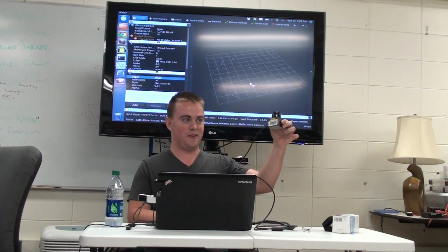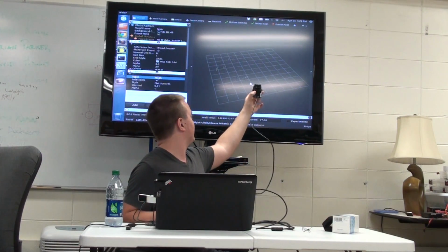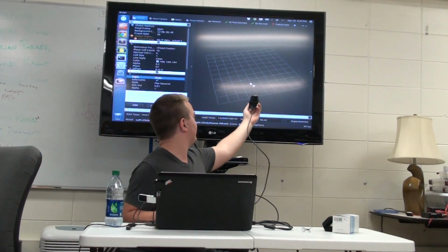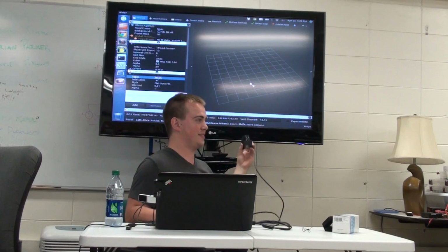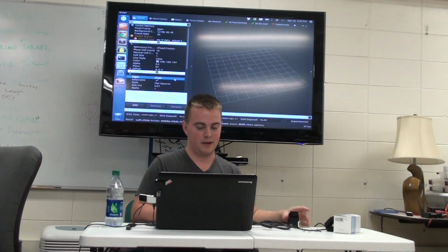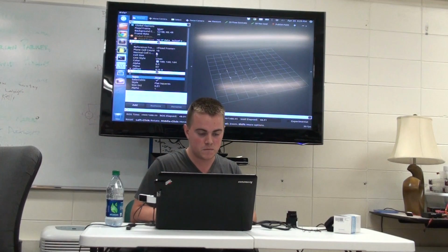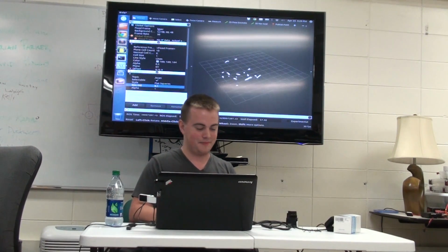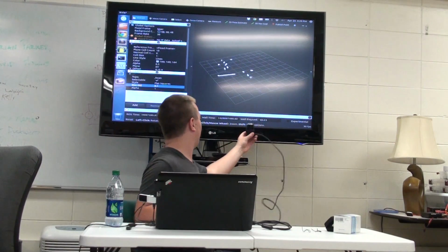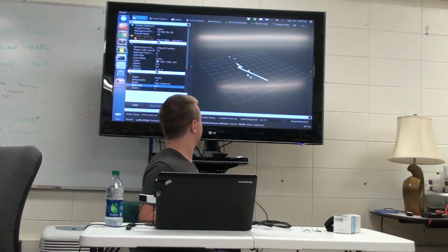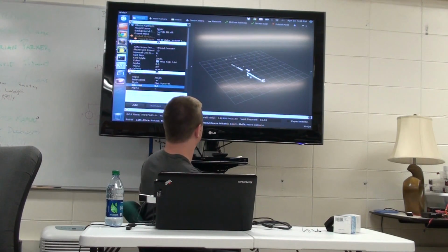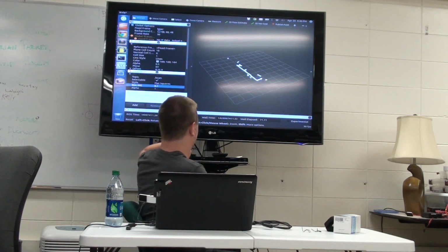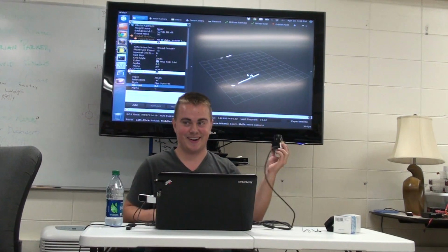You guys probably can't see that very well, but let's see. Okay, so now this is the real-time data the laser is seeing. So I can put it up here. This is not a good place to do this, apparently. It'll be more visible if you change the point size. Yes, the size under laser scan. Right now it's 0.01, so we'll make it 0.1. There we go, that's better. That's more visible. There's not a lot of good walls to see around here. You can actually see there's a computer kind of inset. This is a laser scanner.